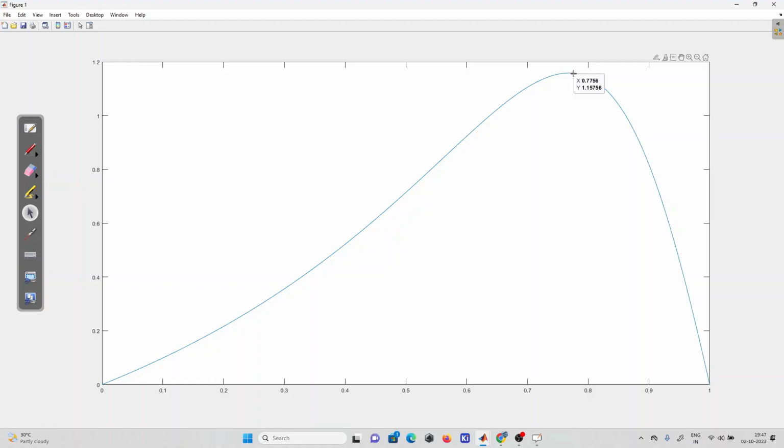See, in this kind of practical resistance, our gain will first go to maximum, then it will come to the minimum value. So in a question, they can ask what will be the stable range of operation of duty for which the converter will work in stable operation. If we operate below this, it's okay, but if we operate after this duty and our gain is low, we can operate at lower duty for the same gain. So it is better to operate on this side. And this will be the maximum range of the duty.